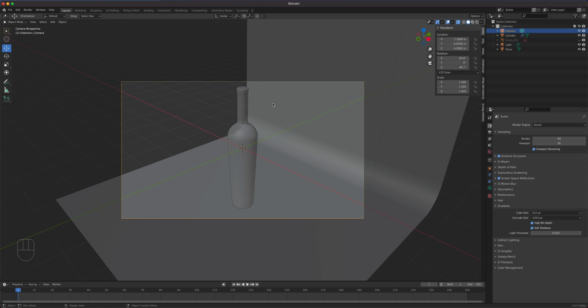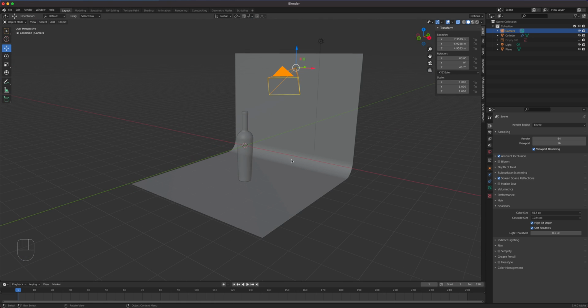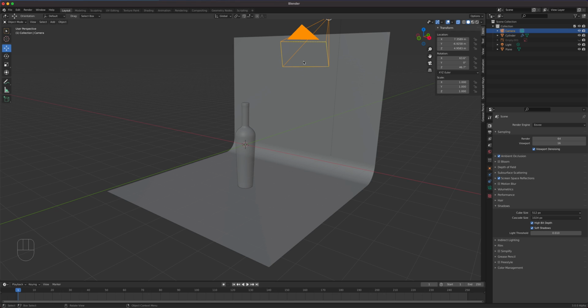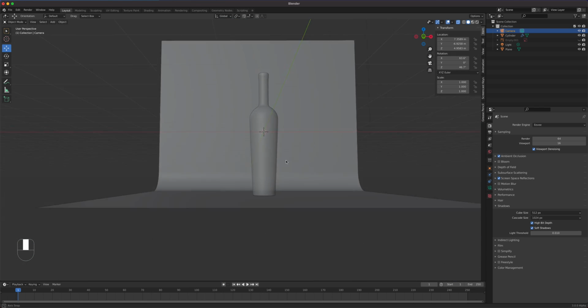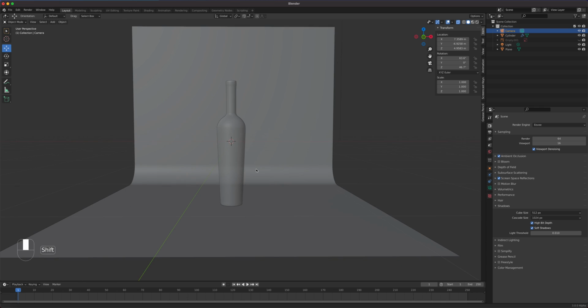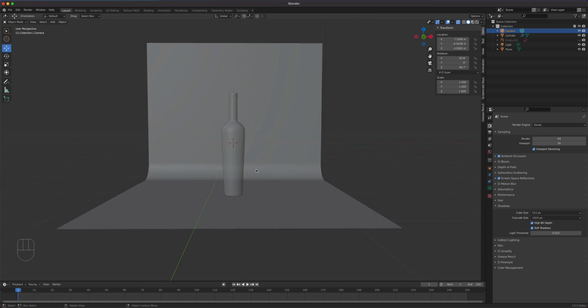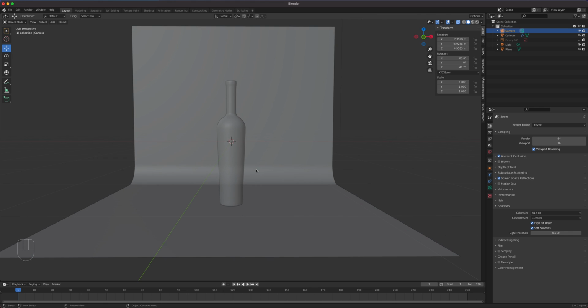So let's control the camera. If I move my mouse right now, it just throws me off. It goes back to the working camera, not the recording camera. If you want to control your camera using the working camera technique, you middle click drag to orbit the camera, shift middle click drag to pan, and then scroll your mouse to zoom, moving the dolly forward and back.